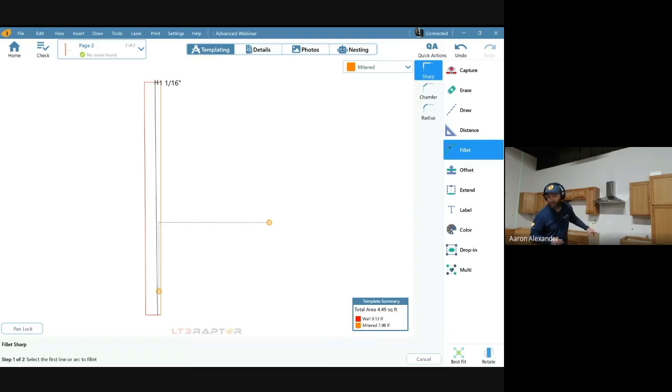Okay, wait, why can't you just use the green sticker and shoot it in that? Okay, good question, Jimmy. So green stickers are for absorption. They cannot always fix reflection. Okay, I just want to make that very clear. You can still be at steep angles and hit the green dot, and it can still throw off your measurement and give you off distances. Okay, I mean, as a trainer, I could tell you, man, I set up and shot this backsplash with nothing on it, getting all the reflection, getting all the absorption, all that.